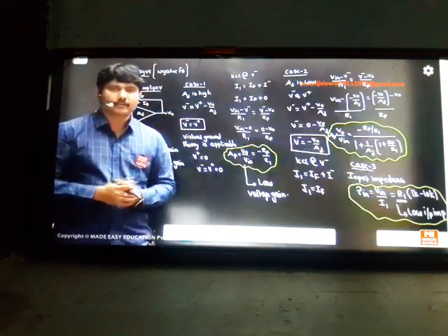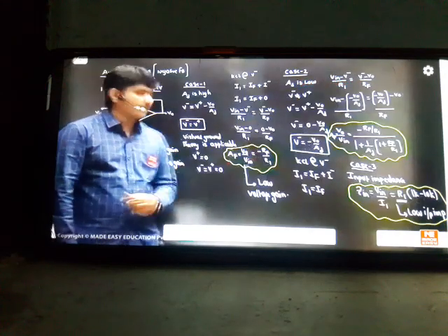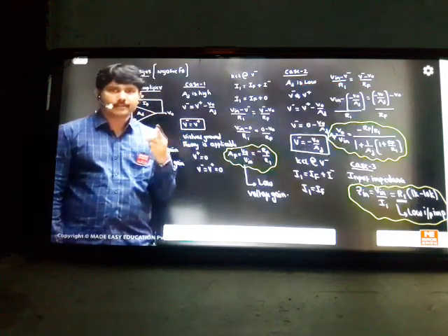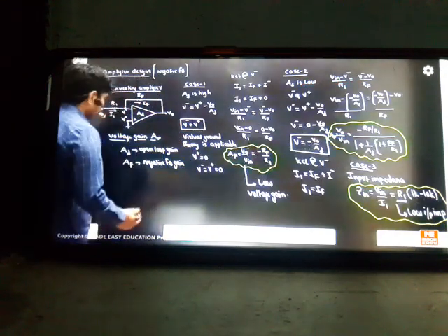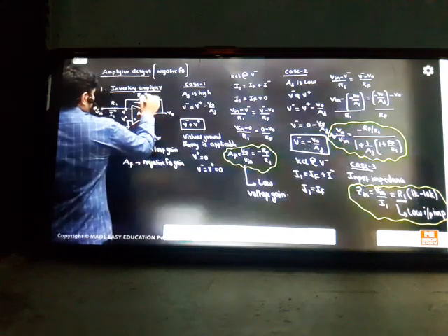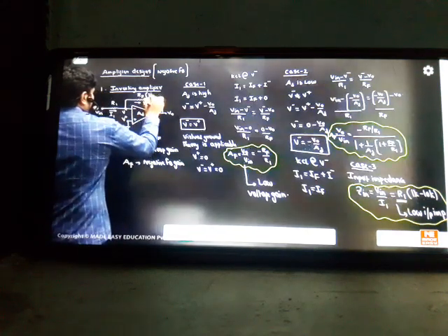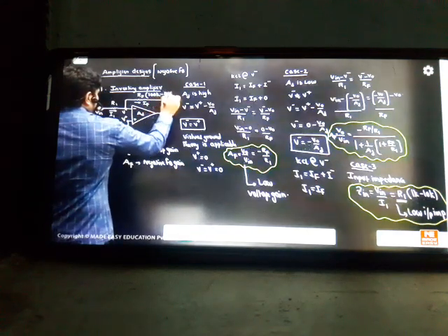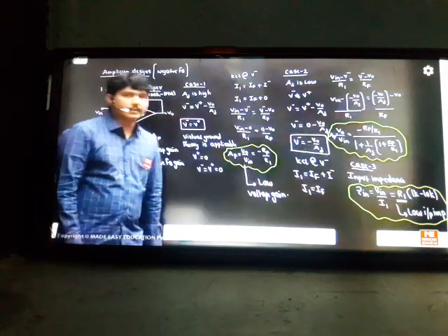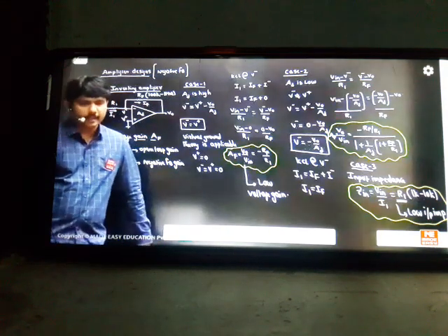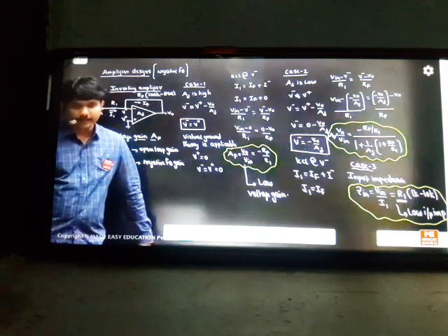In the coming classes called topologies. So their RE, whatever you say, it is R1 here. Their RB, biasing resistor RB, which is a high resistance, here RF. Here RF resistor is high, like your BJT classes. This resistor RF, if you want you can write the range. We take generally from 100K to 1 mega ohm. So RF is a high resistance, R1 is a low resistance. They look like our BJT class RP and RE resistors. Okay, that is the impact of this concept.